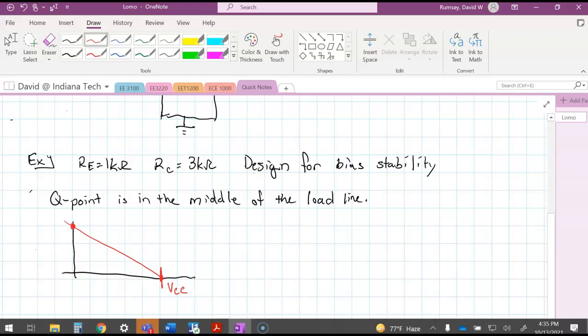VCE is all the voltage dropping across the transistor, because this is VCE and this is IC. Then if all the voltage is dropping across the transistor, there can't be any current, because the current across the resistors would be 0. And similarly here, this is assuming an unideal situation that you can never achieve, where the transistor is turned on and you can pump the maximum amount of current through it. This would be VCC divided by RC plus RE.